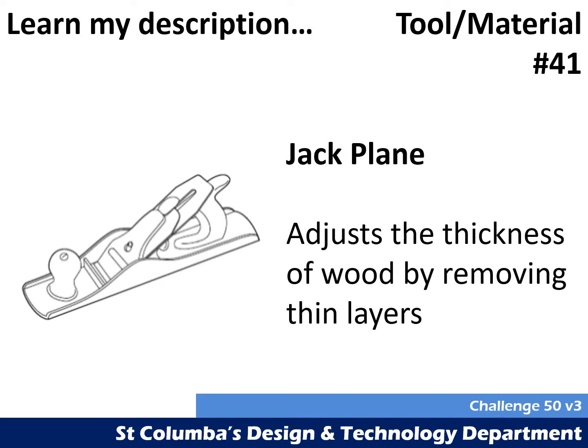The jack plane is used to adjust the thickness of wood by removing thin layers. So a common use of the jack plane for us might be if we were supplied material that was too thick. So for example, if we needed our material to be 18 millimeters thick and it was instead supplied to us at 20 millimeters thick, then we might use the jack plane to prepare that material and reduce the thickness